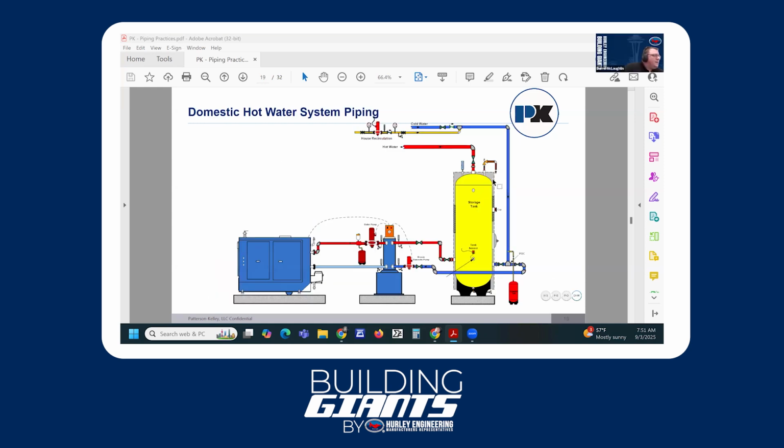Now when we get to hot water, it gets a little bit different, right? This is the same thing. We've got hydraulic separation. We've got a physical separation here. So this is our indirect method of generating hot water. And this heating appliance over here, this could be a heat pump if we had an air to water. Depends on how we do things, right? But as with any heat exchanger, we just need a hot side, cold side. We need a heat input, and then we're going to send that heat out to our tank or whatever we're trying to use that heat for.